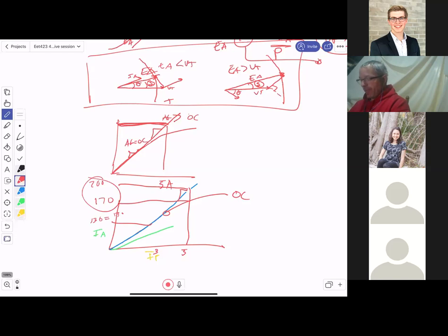So this would mean that your 3 amps is in the unsaturated region of the load characteristics, and your 5 amp is in the saturated region. So you can tell just by looking at the air gap line or looking at the data for the air gap, if the air gap voltage or current is different.